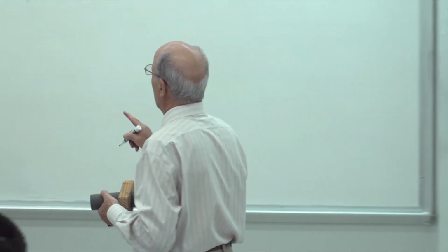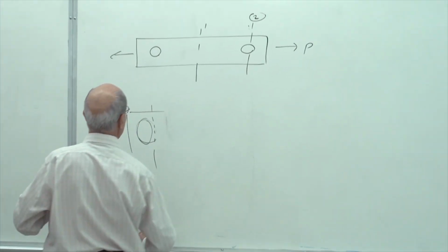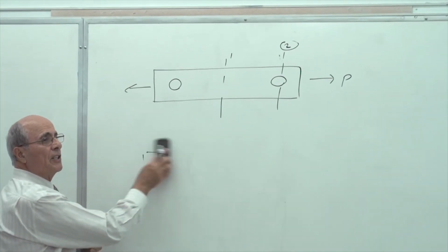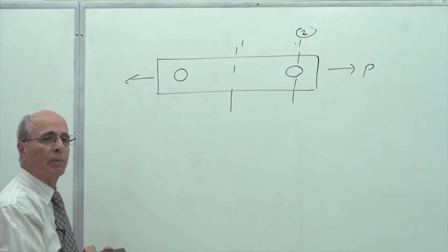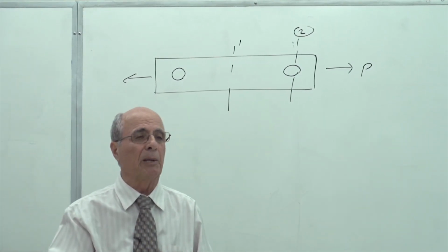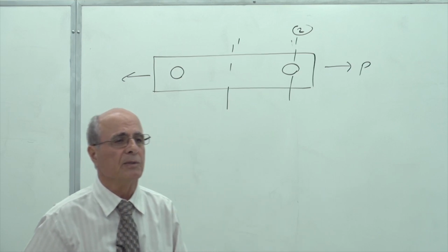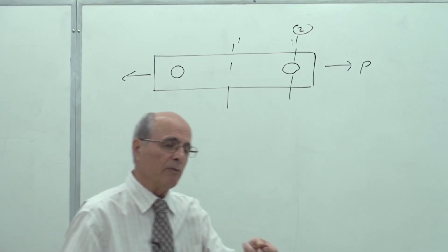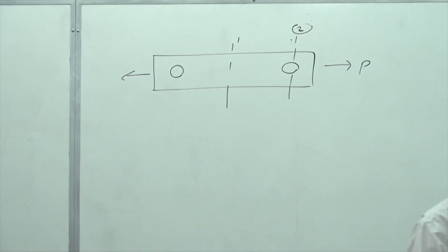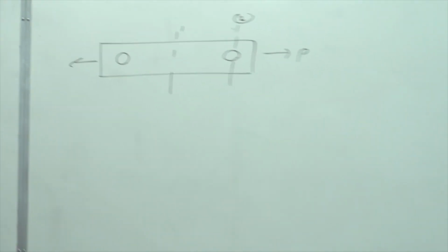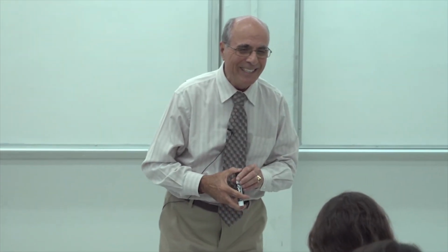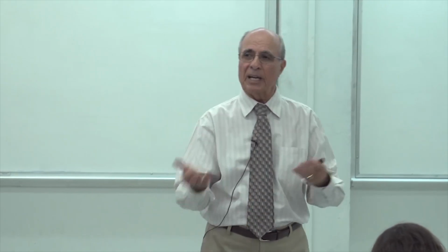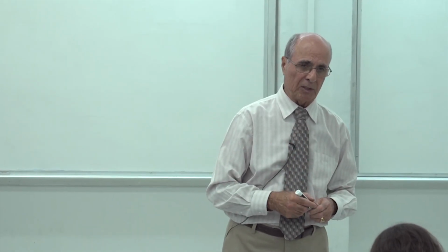That was why your answer was different. So write it down. Subtracting the hole will be only when the rod is under tension, not compression. In compression, actually, the pin is helping resist the load. Is that understood? Yes? So that's why one of your answers was different, because in that homework that you were showing me, one rod is under tension, one rod is under compression. In the tension, you have to subtract. In the compression, you do not have to subtract.